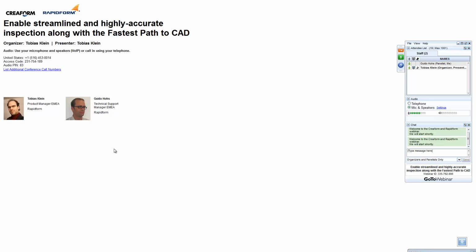Okay, so if you're using a HandyPROBE, as you have seen in the webinar, you could do an adaptive alignment, which is done with several defined points. But you also could use alignments like 3-2-1 if you do not have any CAD, but still want to have an evaluation of your part, which is relying on the axes of the part.